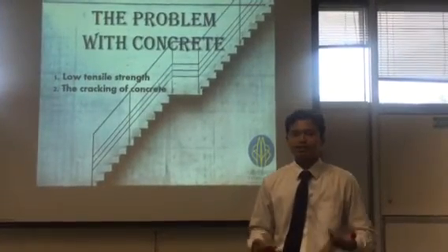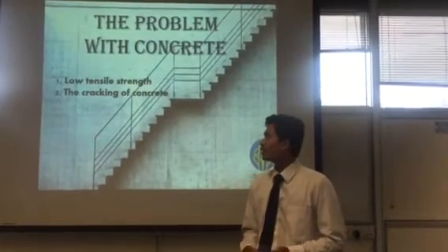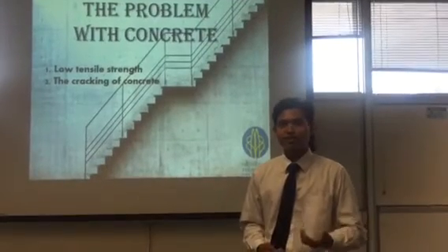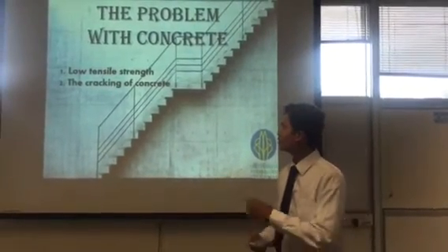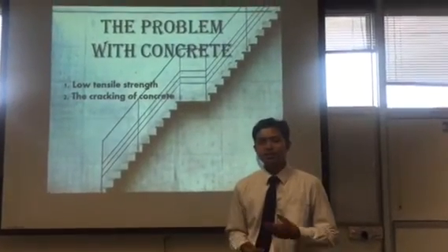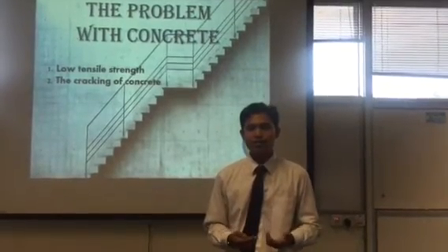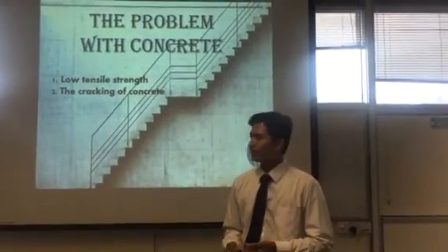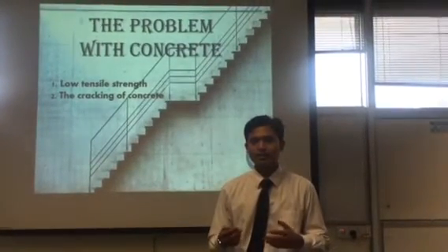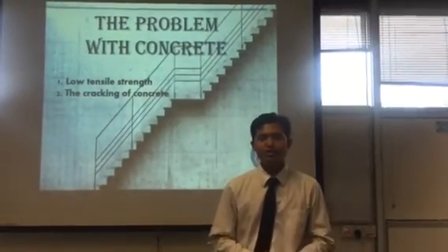So as civil engineers, we all have problems regarding concrete, in highways and hydraulics. In terms of concrete, we have low tensile strength and the cracking of concrete. So how do we counter the low tensile strength? We use reinforced concrete, which is with steel. The problem is, even if you're using steel, it will also crack by the combination of the shear and the force from the outside.